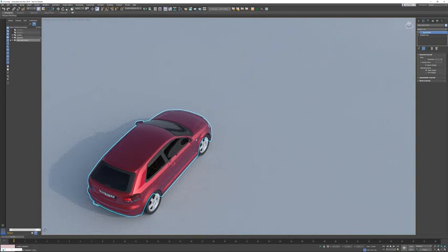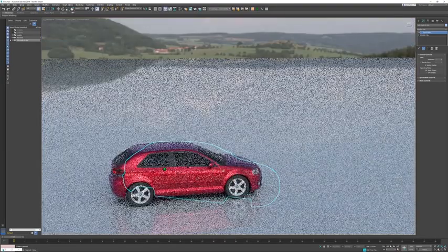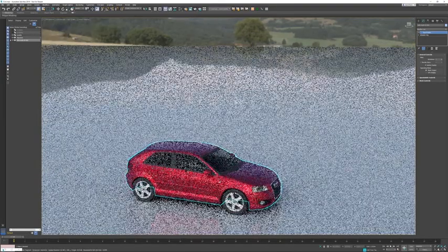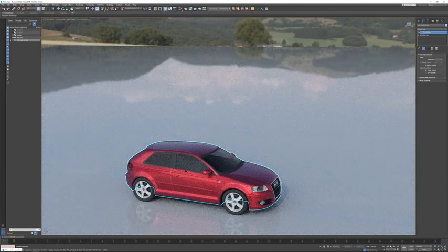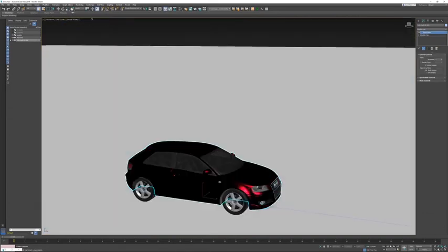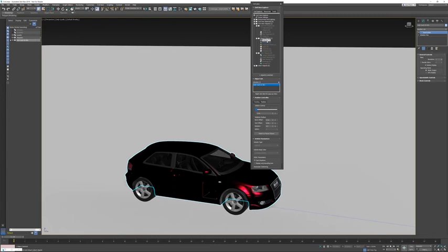And from this particular point of view, I'm also able to save the vehicle to my own car library. There's only one thing you need to take care of, which is that you disconnect the vehicle from the shape, and that can be done in the Civil View Explorer. So if I go to Civil View, Civil View Explorer, this is where all the vehicles are listed. So I'm selecting the vehicle, so that's the Audi.